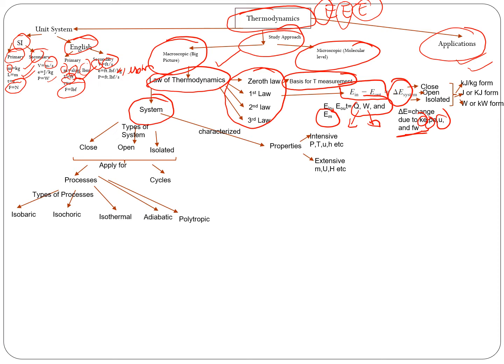And you can see here the laws of thermodynamics can be written for different types of system. So you have closed system in which there is only transfer of energy due to Q, heat transfer, and work transfer. There is no mass transfer. Whereas in open system you have energy transfer due to heat transfer, work transfer, and mass transfer. In an isolated system, there is no transfer of energy, so you don't have Q transfer or work transfer or mass transfer.